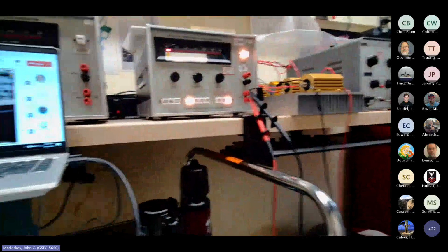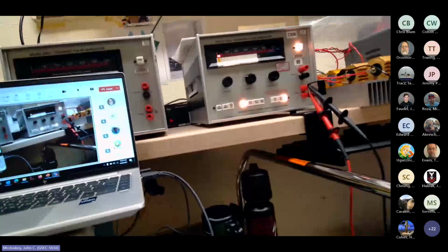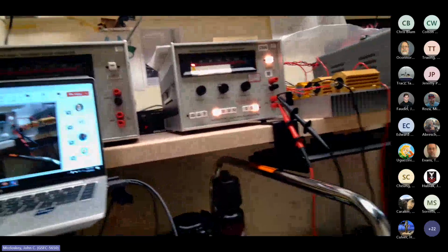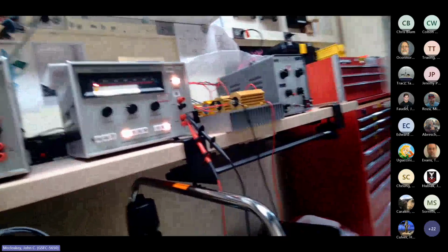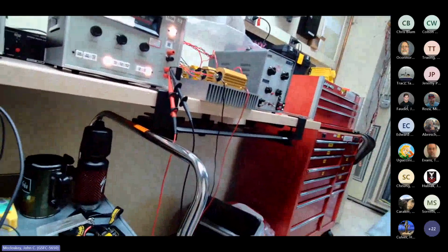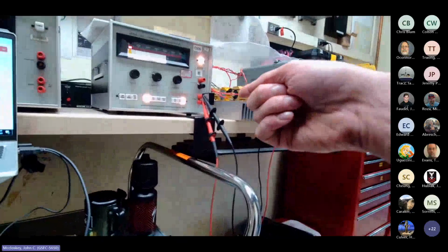But where I was going with this is that if you're doing the 10 microsecond pulse, which is the default, that's what we've generally done. I don't think we've ever even bothered with the 5 microsecond pulse, though you can do it with this machine. But I would be inclined to do this initial pre-cal with the resistor pack. If you're only doing 10 microseconds, then you don't necessarily need to bother with the resistor pack.